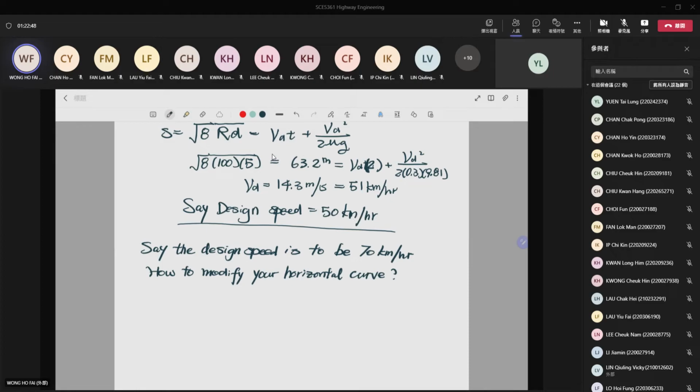Now remember, for this kind of calculation, you are also working in meters per second, okay? So please change it from km per hour to meters per second. Then you can perform your calculations. Here again, you change the 70 km per hour: 70 divided by 3.6 becomes 19.4 meters per second. Okay, this is the speed. So if it is 19.4, what is the stopping sight distance?